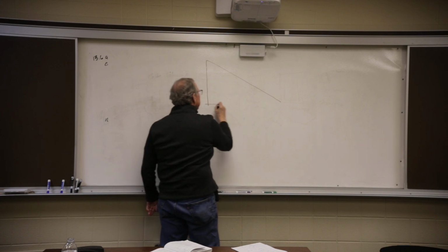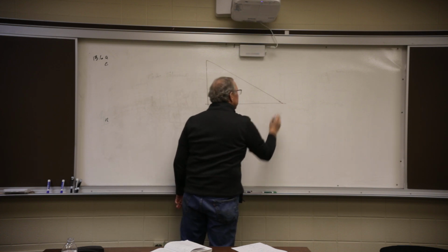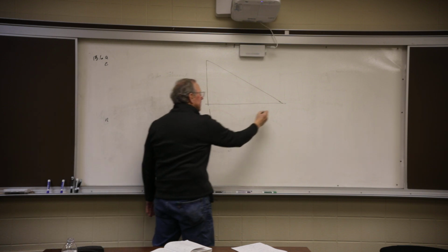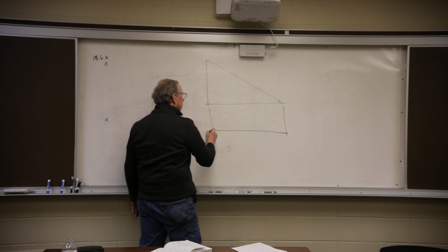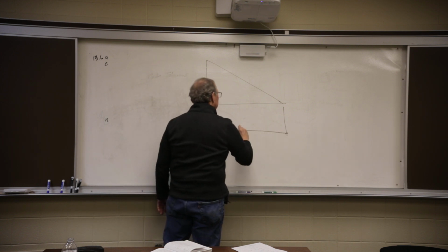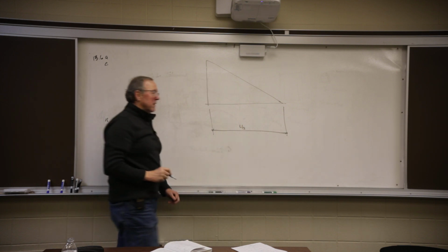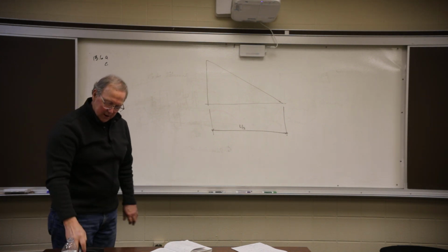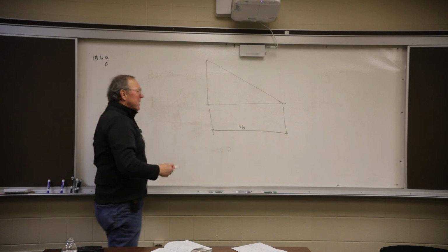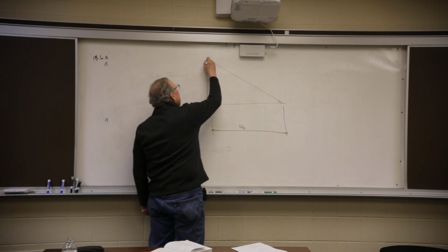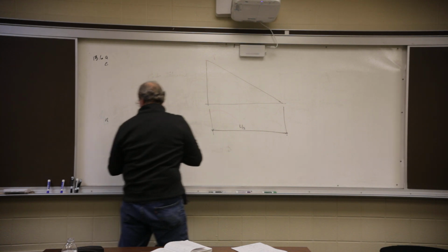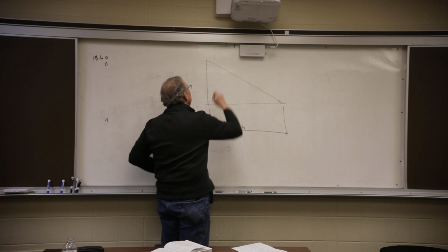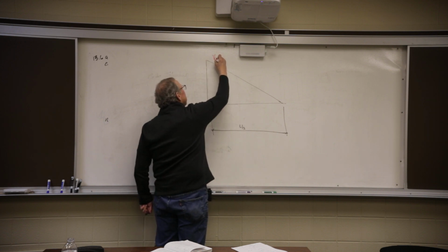And notice that triangle ends up going to the midpoint of the beam, since it's symmetrical. If the beam is L long, the horizontal dimension for that triangle is always going to be L over 2. Okay, so now we've got a triangle that has one dimension. What is the top dimension? That's V max. Okay, V max is the maximum factored shear in the beam.